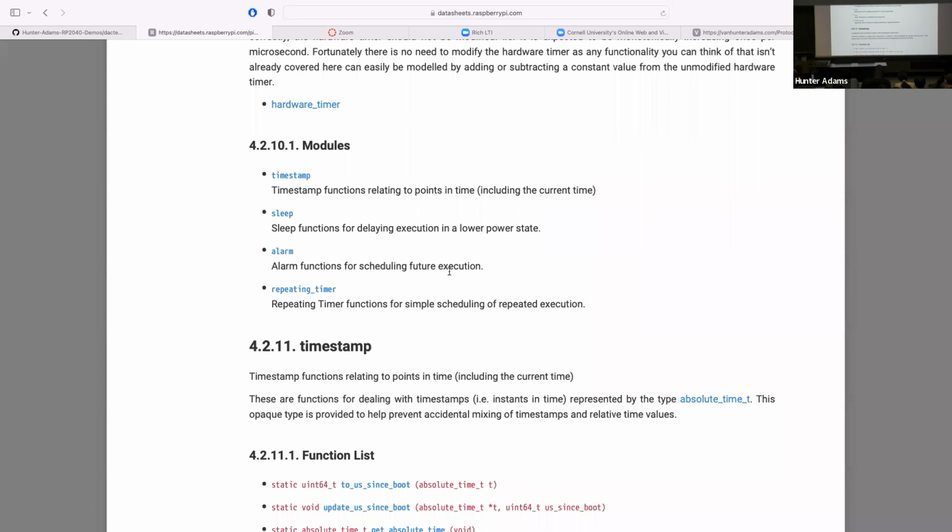What's nice about this is you can set up a whole bunch of different callbacks, all using the same low-level hardware, right? So you're not consuming a whole bunch of your timers. You can associate a lot of stuff with the same timer. The cost of it is it takes you a little bit longer to get into the callback function than it does to get directly into the interrupt service routine.